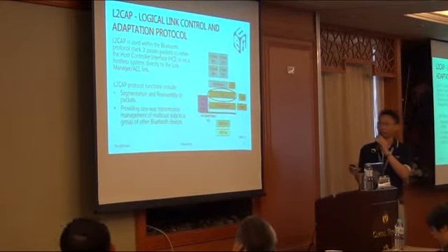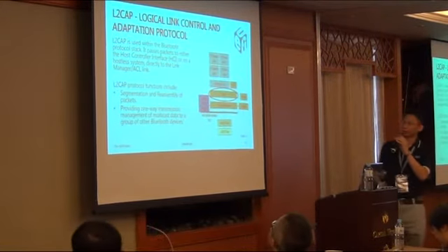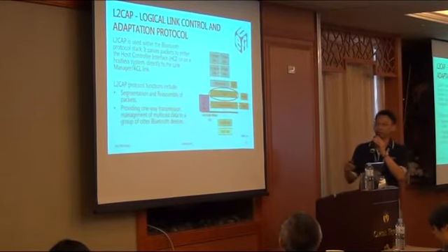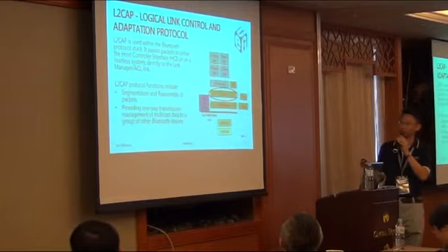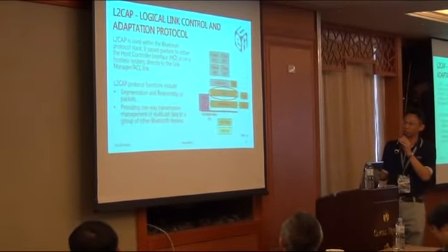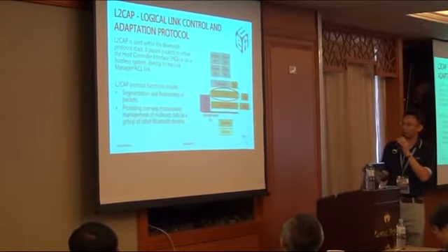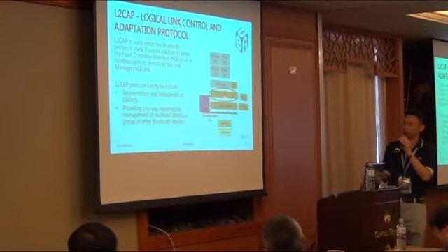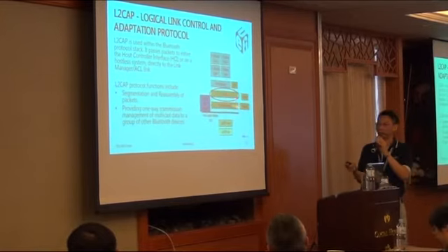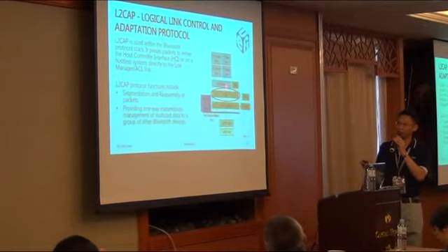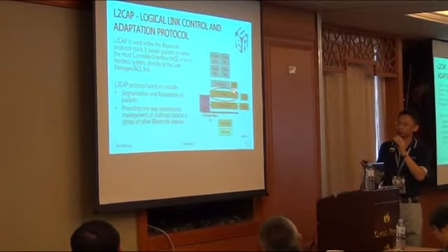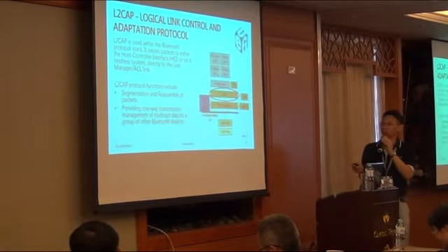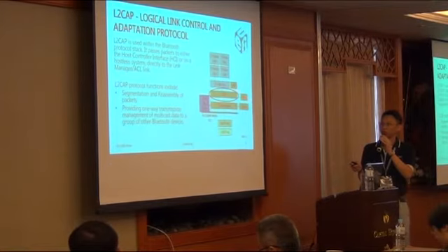So the L2CAP protocol driver provides the same functionality in the Bluetooth bus line. It's called Logical Link Control and Adaptation Protocol. What it does is receive the Bluetooth packet from a lower layer, read the header, then dispatch the packet to a higher layer. Here, there are only two higher layers, SDP and the HID profile driver. SDP stands for Service Discovery Protocol.